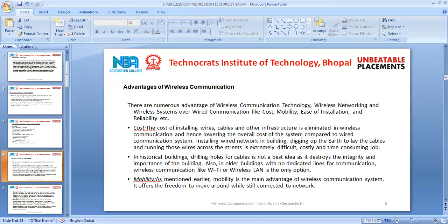The computations follow the link budget computation of the previous section. As a first approximation, we treat the interference as Gaussian. This allows us to treat the interference as equivalent noise, and the minimum SIR takes on the same value as the minimum SNR in the noise limited case. So with all these above six technical challenges, and we have many more, but these are some on the top list.